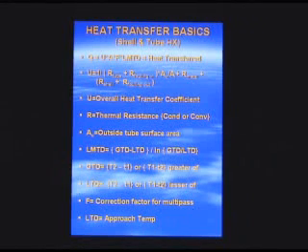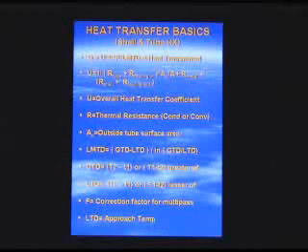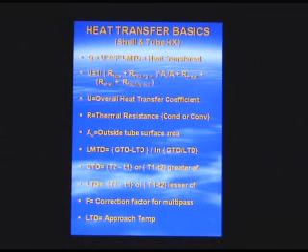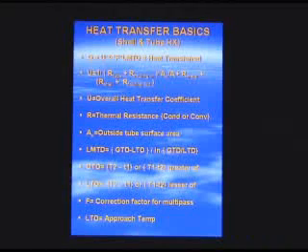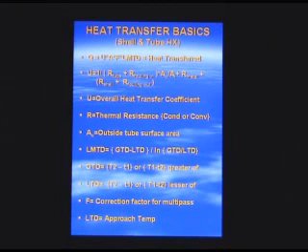Sometimes the client will elect to override a fouling factor to be conservative. Typical fouling factors for most of our streams, we use a 0.002 fouling resistance, which may not seem large, but if we have a very high heat transfer coefficient, that will significantly reduce the overall coefficient.